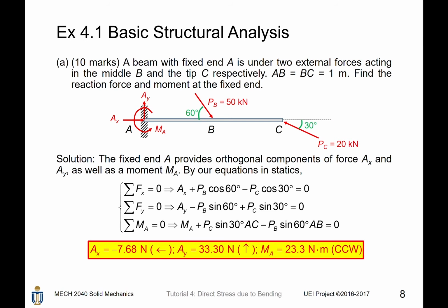Apart from that, we also consider the moment about point A. We know that when PB is decomposed into orthogonal components like this, the horizontal component will provide no moment to this fixed end. The vertical component will provide the moment with the arm AB.